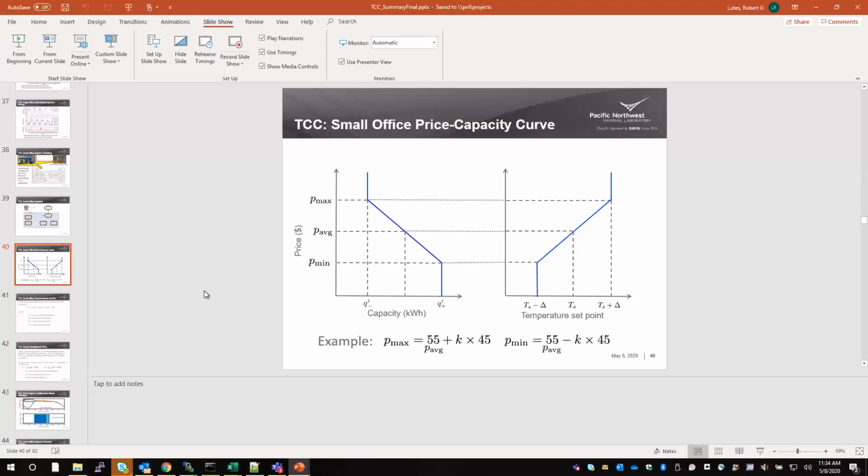So still, it really depends on where you want the opt-out to be. If you want that to be at the application level where you're handling that at the VAV, you can do that as well by turning off actuation. And I already mentioned that there's a mechanism for sending a message to the agent that basically turns off actuation. Or if you say, okay, we don't want to turn off actuation for this agent, but the building operator at the BAS, as Srinivas mentioned, can selectively pick certain zones. Say they know that a conference is happening in one of the rooms. They say, okay, we know that we want to keep this set point at a certain value during this conference.